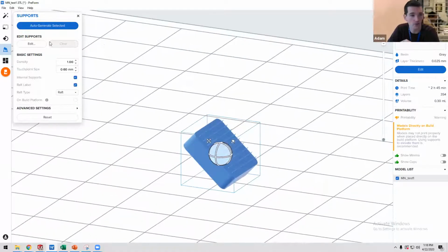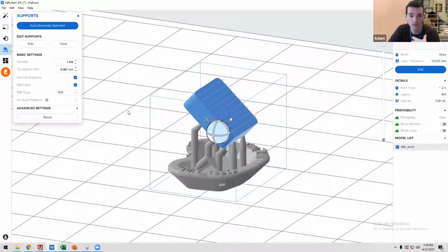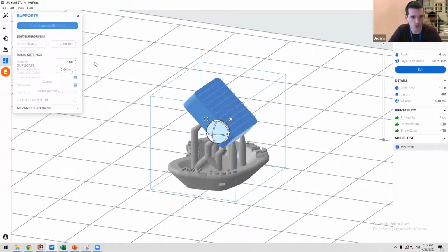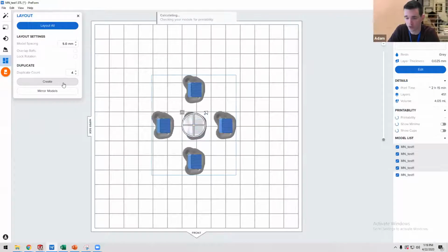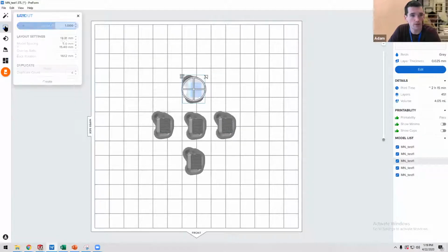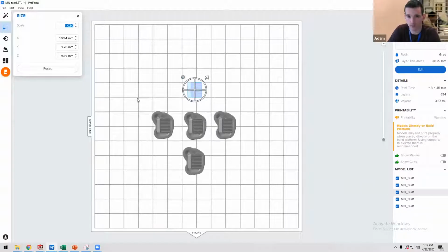And if you're sending this to the Mechie team to do printing, then there's some more options I'll show you. I can duplicate this. I'm gonna make 5 of them total, so throw a 4 in here. I'm gonna scale them like I told you. So highlight one, scale, and do like 1.03. That'll be 3% bigger. Maybe one is a little bit smaller, 0.95, something like that.